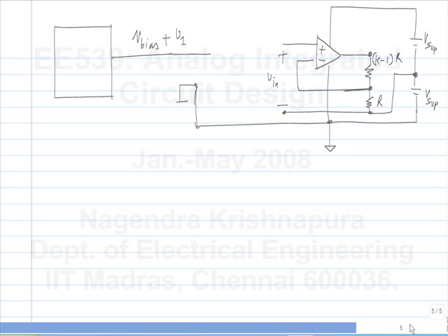What's that? No, first of all, V1 may not be an AC signal. It could be a DC increment above a bias. Okay. I don't want AC coupling either, because I want the DC value of V1 to be applied to the amplifier. Okay.